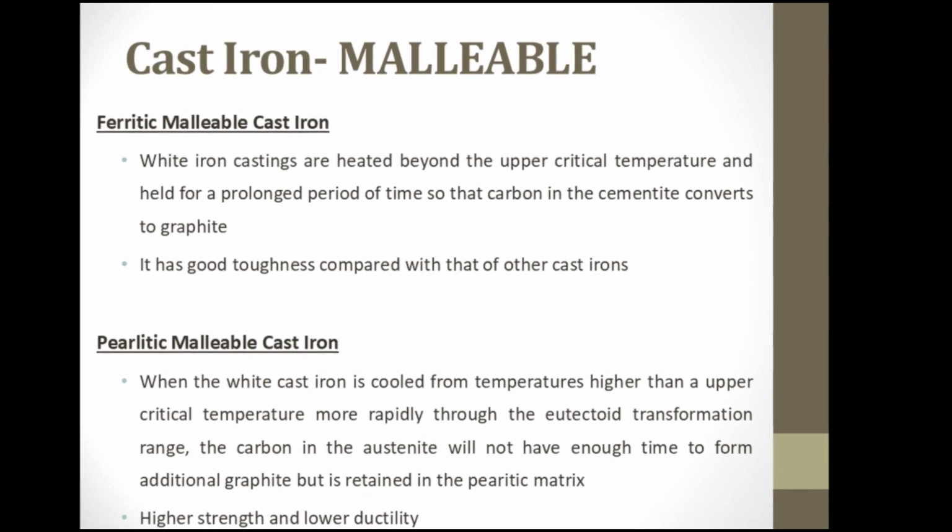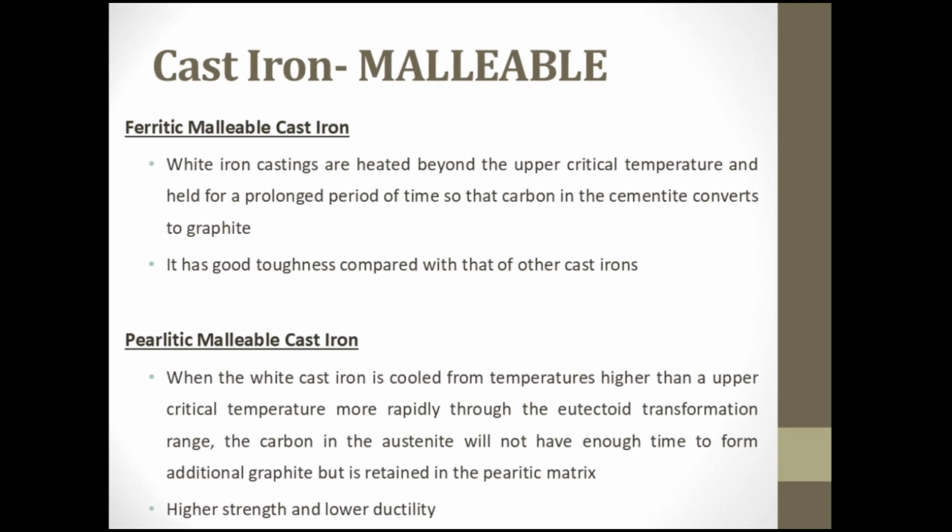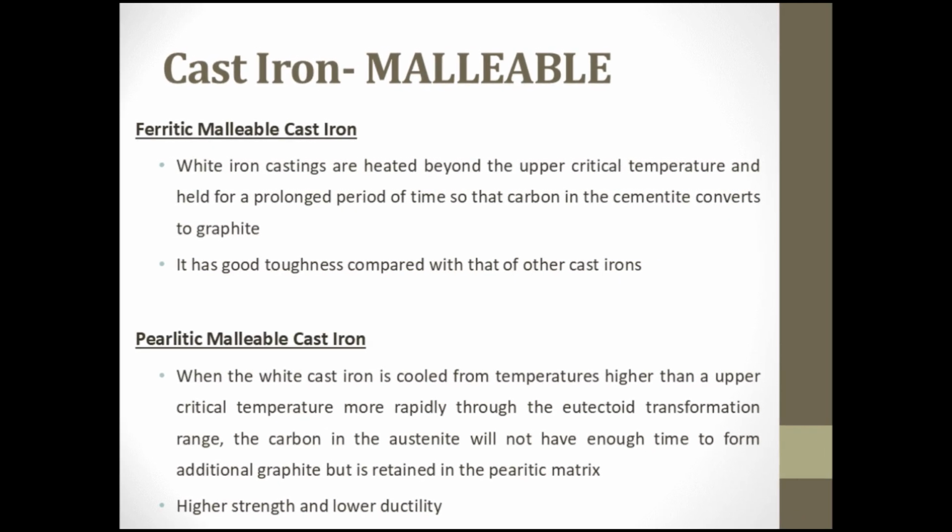Cast iron malleable, ferritic malleable cast iron. White iron castings are heated beyond the upper critical temperature and held for a prolonged period of time so that carbon in the cementite converts to graphite. It has good toughness compared with that of other cast irons.